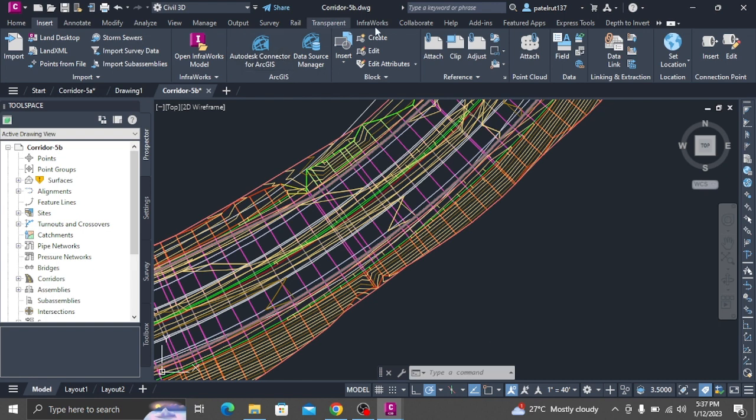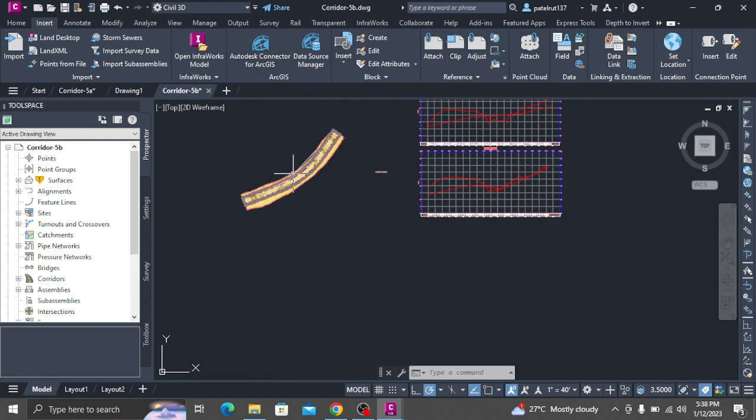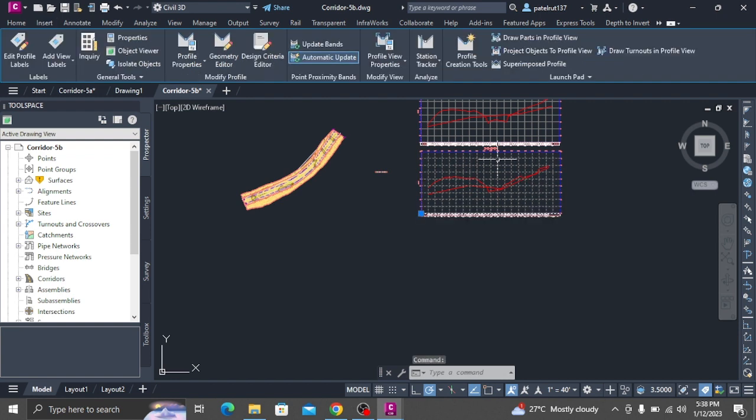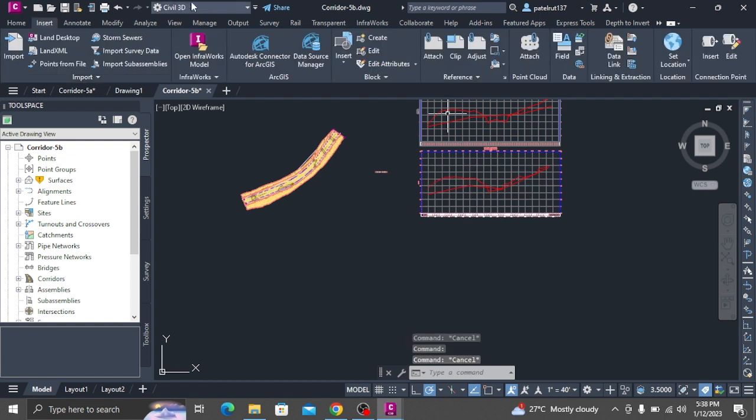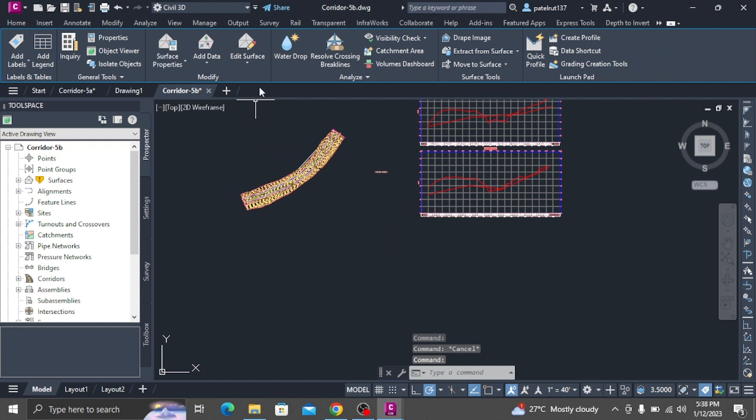Repeat the previous procedure to define the inside boundary of the paved region. Click in Circle 1 and select EPS to define the left outside edge of the paved shoulder. Click in Circle 8 and select EPS to define the left outside edge of the paved shoulder. Click in Circle 2. On the command line, enter C to close the boundary. Change the name of the boundary to Pave Inside. Change the use type to Hide Boundary.